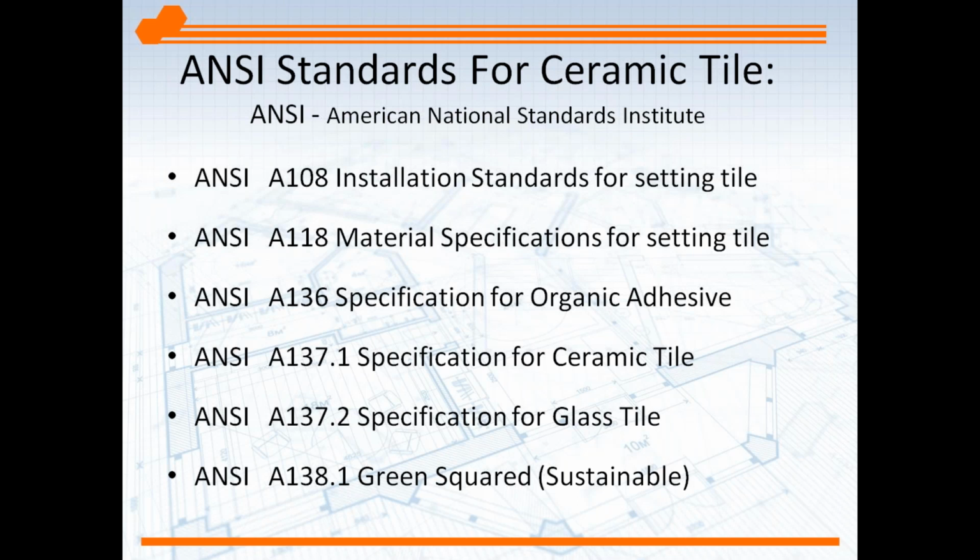The 136 standard, about the middle of the page here we're looking, is organic adhesives, what we know traditionally as mastics in the industry. 137.1 is for ceramic tile, which would include your porcelains, of course. 137.2 is glass tile, and 138 is the Green Squares sustainability standard.